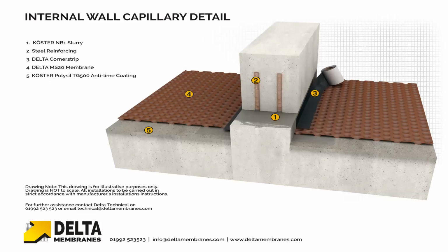If it's an in situ concrete load-bearing wall which divides the basement, well, instead of using a physical DPC, we'd use a crystalline slurry, which is your figure 1 there, to provide the waterproofing continuity through that wall, because it's acting like a DPC, isn't it? Because we've got a capillary damp problem potentially coming up the wall of rising damp. So the slurry there is suitable to go within a concrete construction joint, but it's also adept at stopping water rising. So we've got our continuity there.